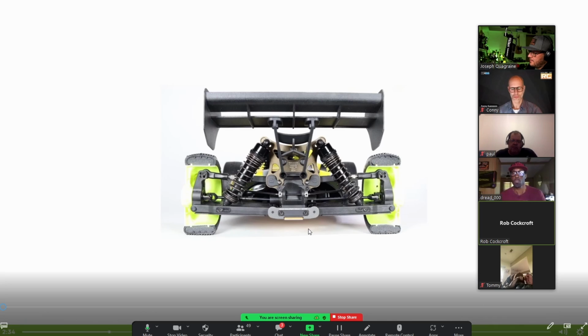You can have the same static roll center height, but as soon as the suspension moves, the roll center moves also, and that's not going to be the same anymore. So I get you. So it's changing the roll center migration left to right, so effectively by changing that swing arm length. Exactly. So it changes the geometric roll resistance and also camber change. So it won't be the same. Even if at that one moment with the car set to ride height, the roll center could be in the same position, but handling won't be the same.